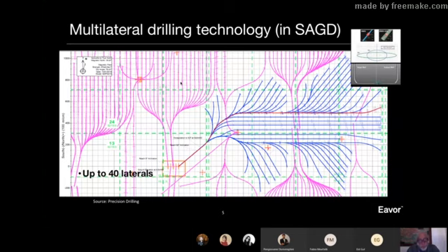And in rocks that you don't care if they're permeable or not, because you're going to use only conduction. So you can drill also in clays. And you don't need to have very high permeability. Actually, you don't want to have high permeability, so that you're sure that you're not interacting with your geothermal aquifers.